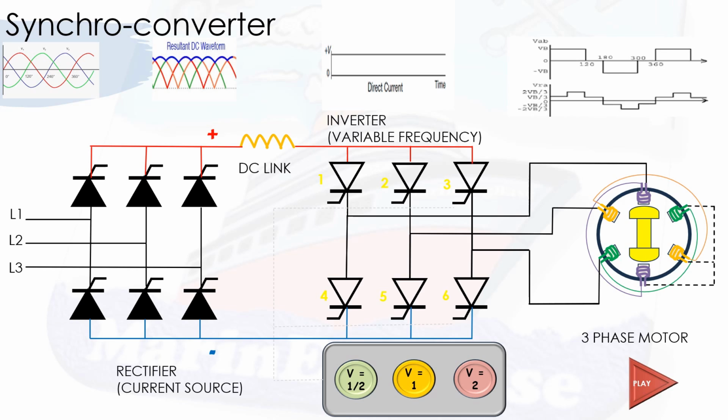Let's activate the half speed first. In this case, we can see the firing takes place at a slow rate. The commands given by the circuit to each pair of thyristors are at a slow rate, so the varying or rotating magnetic field takes place slowly, which causes the rotor to spin slowly.